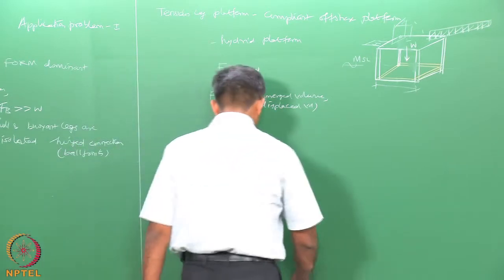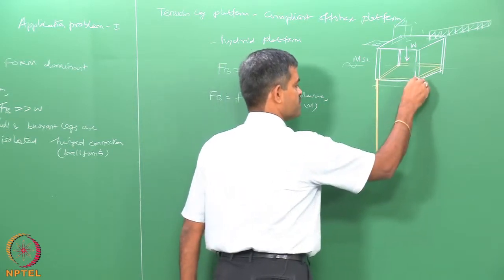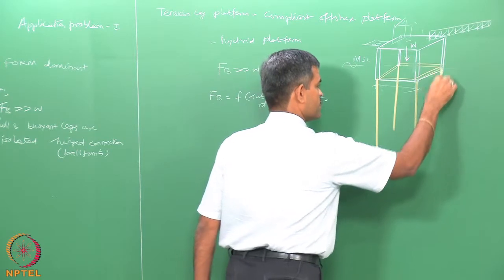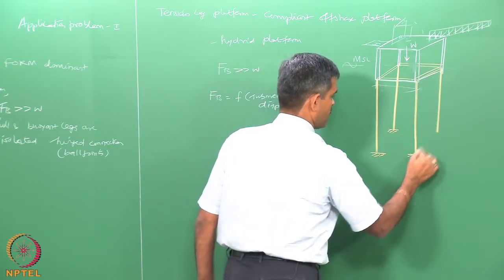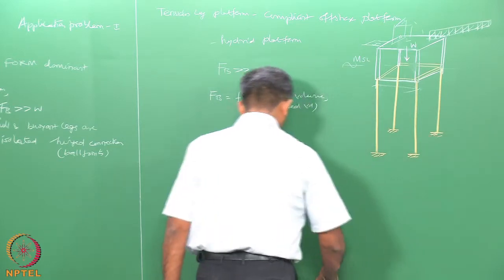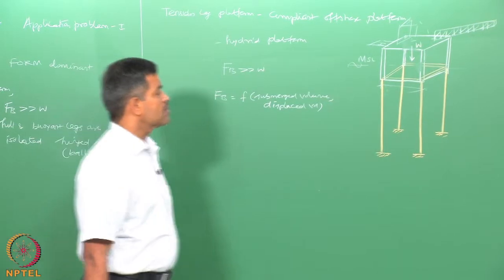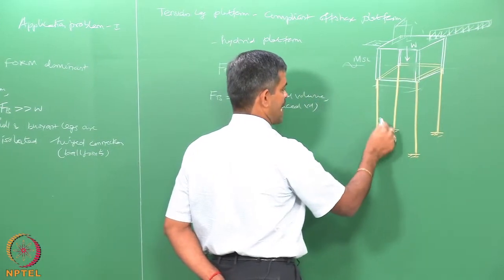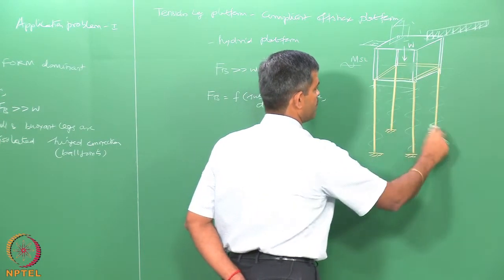So, we hold down this platform using tethers, which will be supported at the bottom and anchored to the seabed firmly. So, when the platform is brought in position, these tethers will all be slackened, all will be loose, there is no initial tension in them.